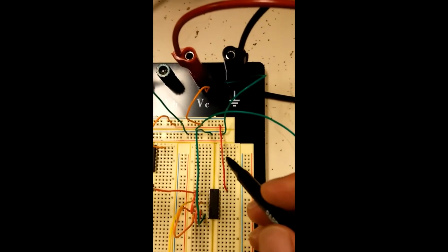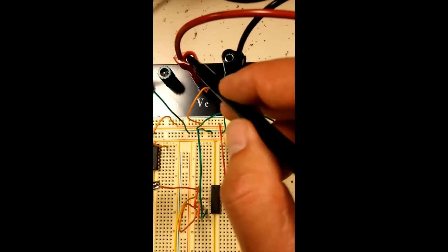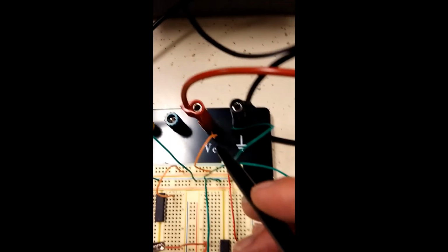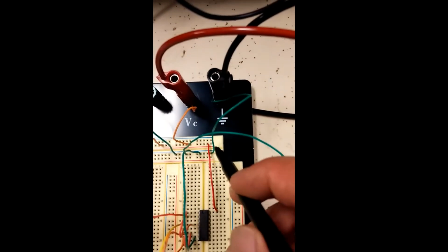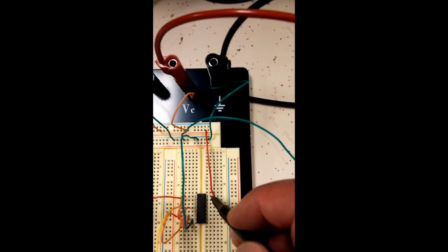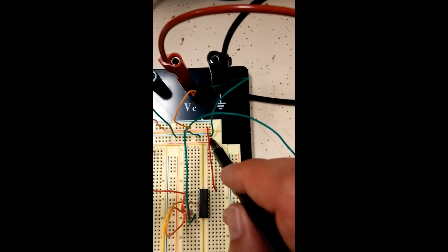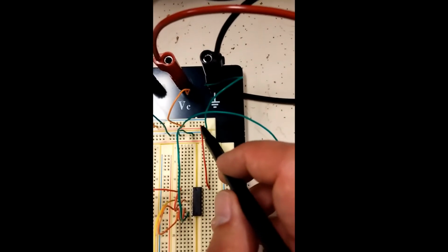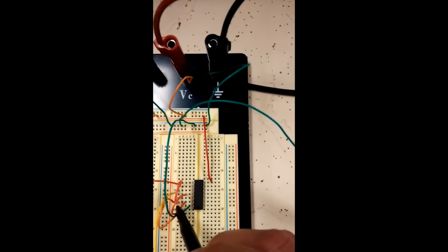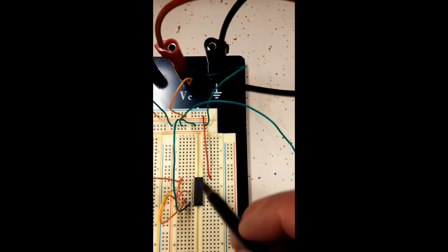So according to this picture, we're going to construct this circuit. This is what I have built. So the power from the DC power, I set 5 volts normally for this IC. So 5 volts is a very common voltage for the IC. And of course we have the ground. So this is connected to 14, ground at pin number 7. Make sure I have the right, yes, 7.